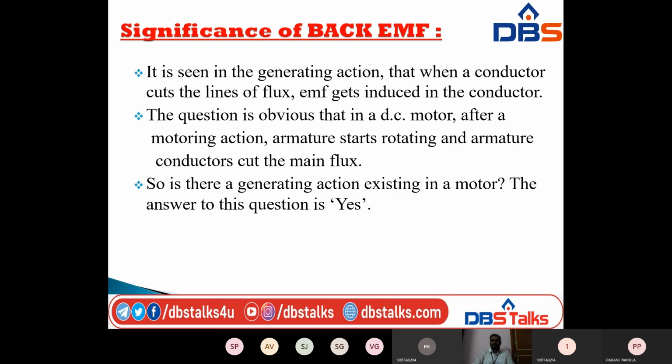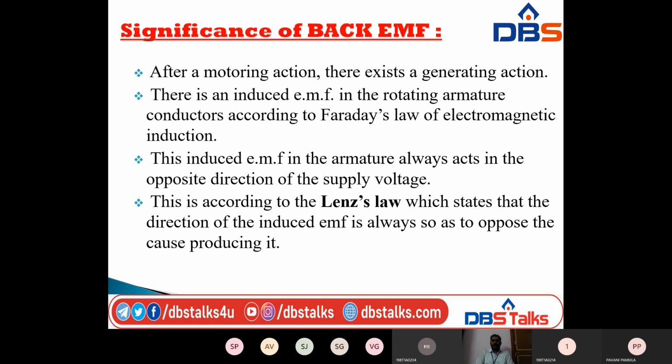The question is obvious: in a DC motor, after a motoring action, that is after converting the electrical energy into mechanical energy, what will happen? The armature starts rotating and the armature conductor cuts the main flux. So is there a generating action existing in a motor? The answer to this question is yes. There exists a generating action in a motor also, after a motoring action.